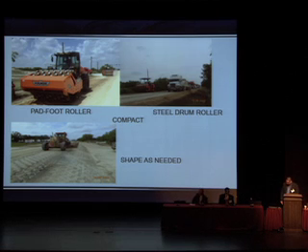Okay, immediately behind the water truck, since we were treating an 11-inch layer, is the roller, and in this case we used a 20-ton pad foot roller followed by a 20-ton steel drum roller. We were able to get compaction in 5 passes. And this was verified by Tom Scullion and his group, doing some dynamic cone penetrometer tests at every inch.